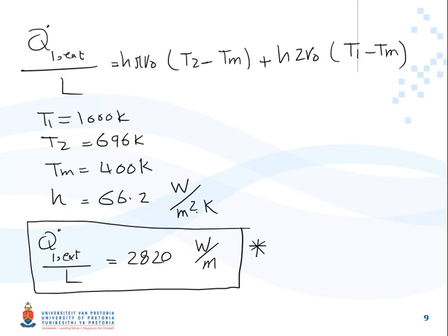The only problem we might have is calculating h, the heat transfer coefficient, but we also know that it's related to k, Nusselt, Prandtl and Reynolds numbers, and we can find all those correlations. It's a little bit of work, but far from complicated.